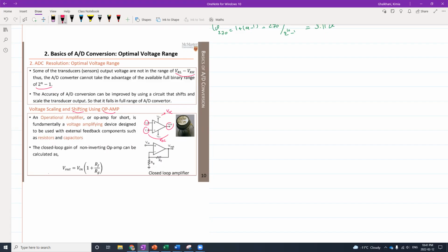When you are using field effect transistors, which we call FETs, inside the op-amp, that's when they label it as VDD or VSS. That's the reason for seeing different labels for these terminals, but these are generally the terminals for the power supply.